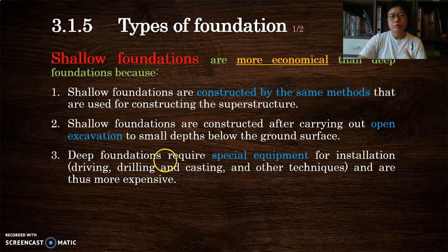You need special machinery. For example, bored pile. Bored pile is not so simple as just bringing the pile, popping it in, and that's it. No, you have to drill a hole. You may have under-reaming to make a bigger base, for uplift. Then you take out all the soil, all the spoils. You have to find somewhere to throw them away. You can't just throw it onto your neighbor's ground. Then you put in the reinforcement, adjust and line them properly. Then put in a tremie pipe to put in the concrete, compact the concrete, and make sure that everything is aligned. So it's quite a bit of work there, and it could be quite expensive and time consuming. Alright?